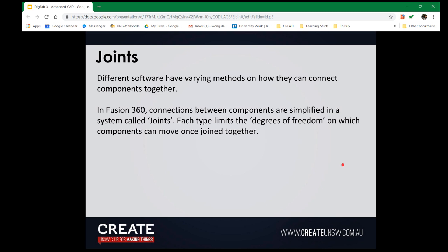The maximum motion you can achieve is 6 degrees of freedom, because you can imagine I can translate, so I can move forward, back, left, right, up and down, and I can also rotate in those 3 directions. So you'll learn that you'll get 6 degrees of freedom for any motion. And what we're doing with these joints is we're limiting the amount of degrees of freedom based on what joint we use, okay? So we'll do a simple joint, we'll do the render, and we'll jump back and I'll show you some other joints as well, okay? But that's the premise of joints.